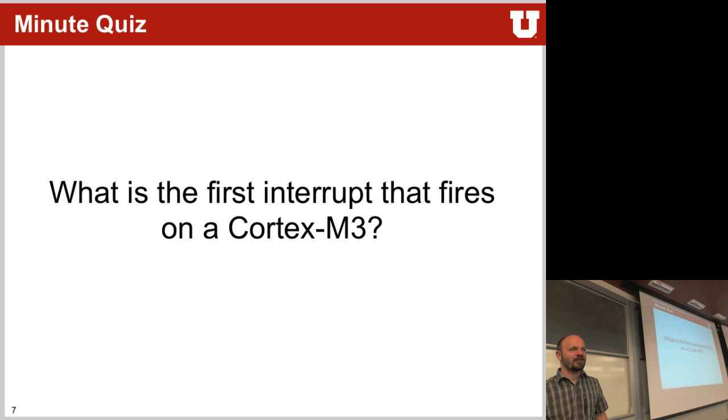So what is the first interrupt that gets fired on a Cortex M3? Reset. Yes, reset. The system, when it boots up, first reads the stack pointer and then goes and fetches the reset vector handler from address 4. So it's executing the reset interrupt.